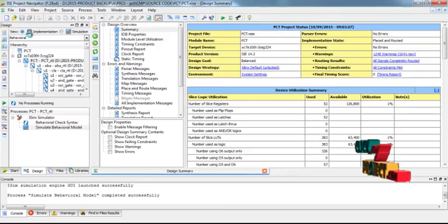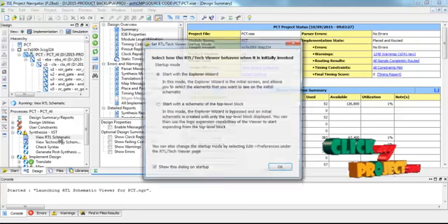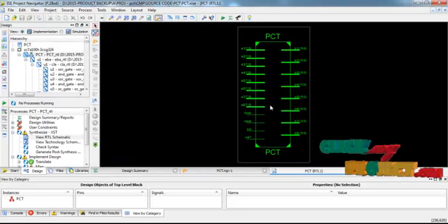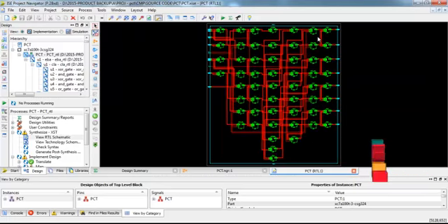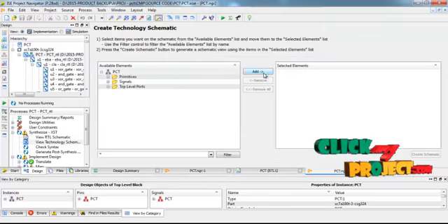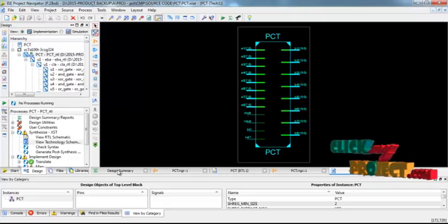Then we go to the implementation architecture. The implementation architecture lets us analyze the RTL and technology diagrammatic representation for our VHDL code. These are the transformation architecture blocks for the logical diagram operations. Then go to the technology diagram. The technology diagram represents the FPGA kit implementation for the overall architecture.